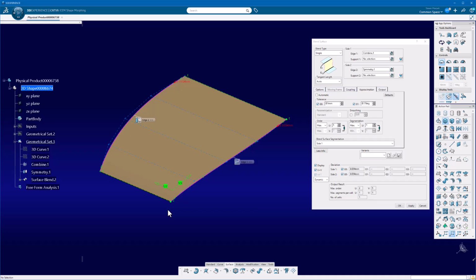So the tolerances in CATIA, ICEM shape, so on, by default are at a micron, 0.001. And for some things, I want that. But for this, I don't care. It's close enough to the curve. It's close enough to that shoulder that I put in that theoretical. And I got a smoother, cleaner surface. So these approximations allow you to specify, well, really, how complex do I want that curve or surface to be?